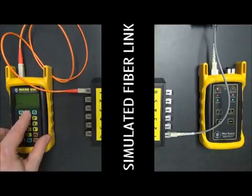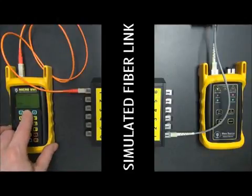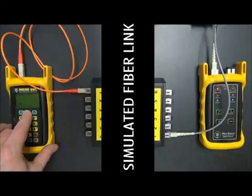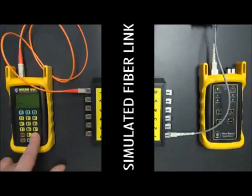Because this is the first fiber test that we're doing for this job, we're asked to enter a label. Now this label is simply a prefix that describes the fiber length that you're testing today. It's just another way of naming it. The micro owl will automatically put a port number after this label. So the number 1, for example, will be the first port number that will be saved. So it'll put a number 1 after it. Once we're done entering this label, we simply press the done key.